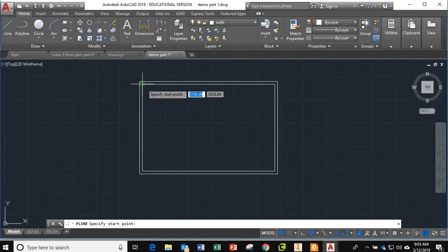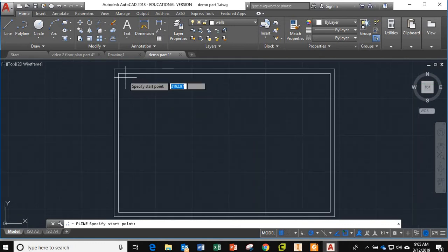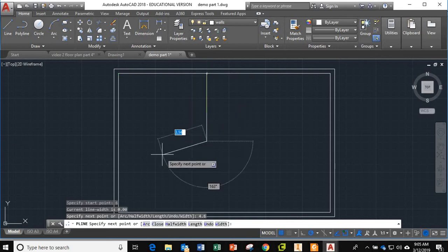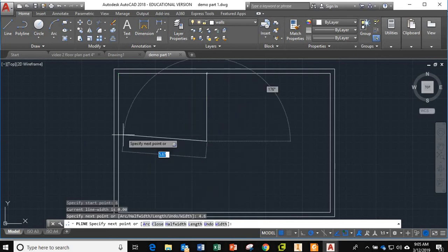There's several right ways to do this. Let's say I want to start a wall that is 6 meters from this edge. So I put my cursor over here, move it. Let's type in 6, enter, and that makes the starting point 6 meters from that point there. And now I want to go a distance of 4.6, and I want to move over until it snaps perpendicular.